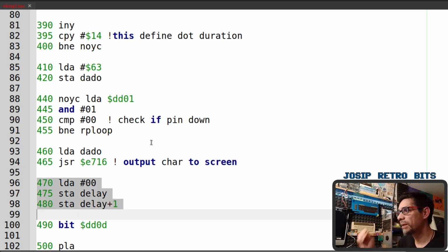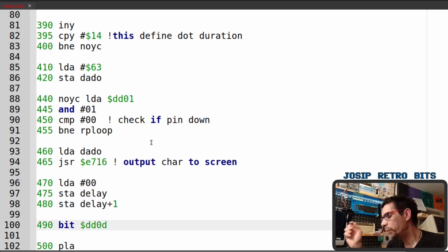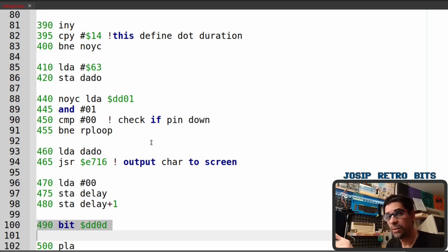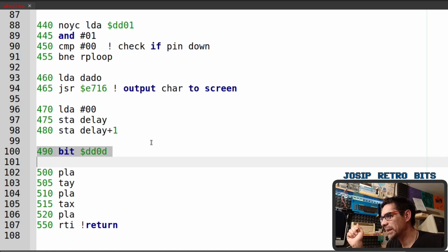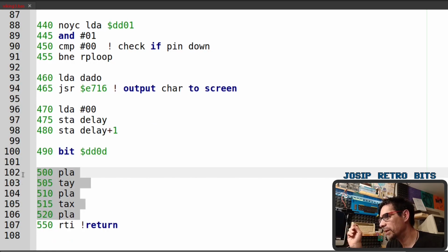So firstly, we will again reset our main counter. We acknowledge that the interrupt has happened, and that means that the next interrupt can happen. And before we exit our interrupt routine, we are doing this, like I mentioned before.